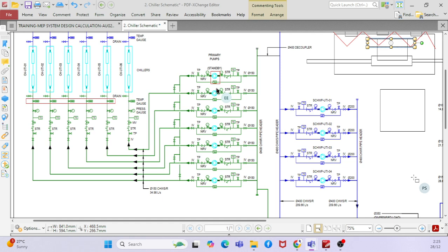So typically your chilled water flow can change, which will be controlled by the PICVs of the individual equipment on the air side, and accordingly your chilled water flow gets fluctuated. So what would typically be 50 liters per second can become 30 or maybe 40, depending on the type. Correct, right? So when the flow rate changes, what will happen? The chiller will not get sufficient flow, right?